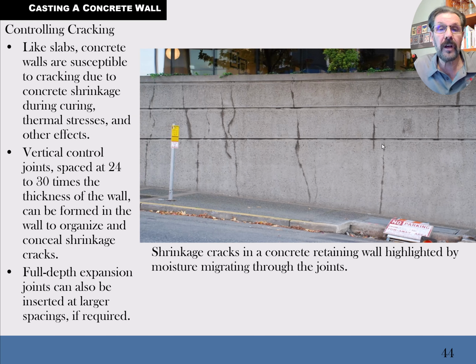Okay, here's some flaws in this retaining wall where they don't have proper drainage behind it. And so all these cracks in the wall are showing water migrating through. Some of these cracks are probably forming because of the excess forces of water. The force of water doubles the forces behind that wall. And so it's another reason why you normally have to have drain rock behind those walls and drain tile to send that water somewhere else to reduce the hydrostatic pressure of that water on that wall.